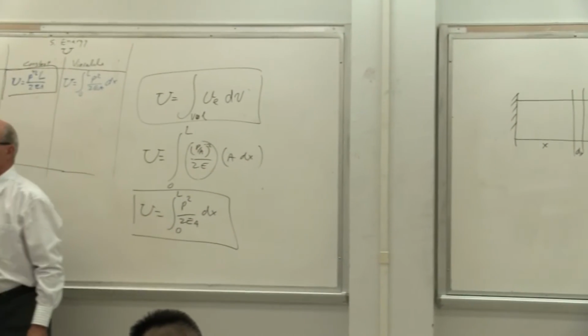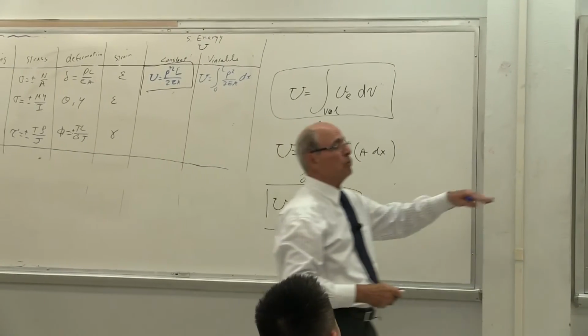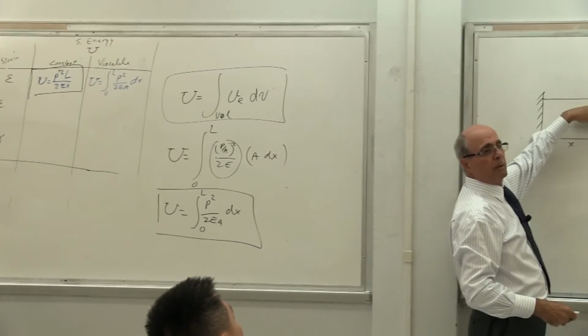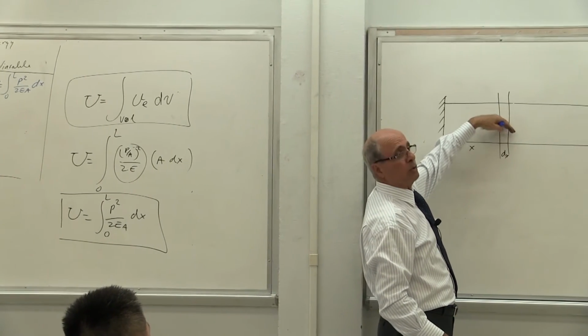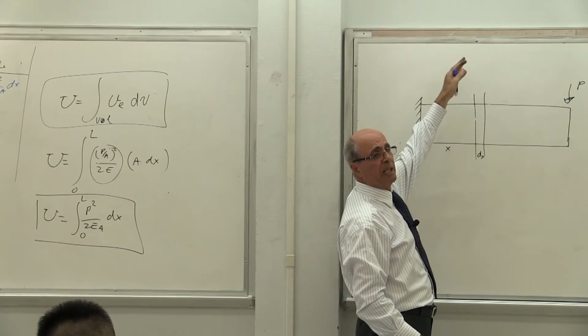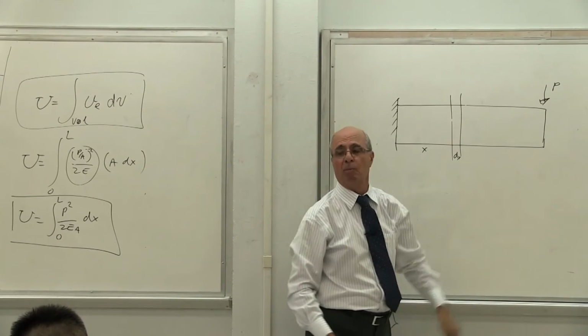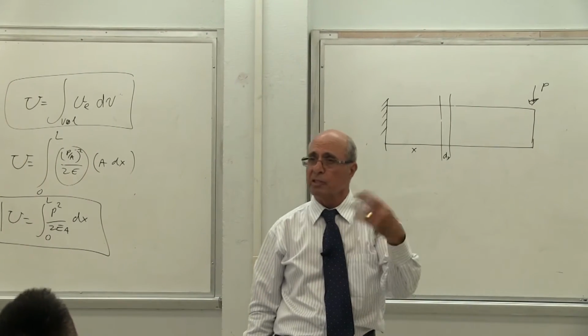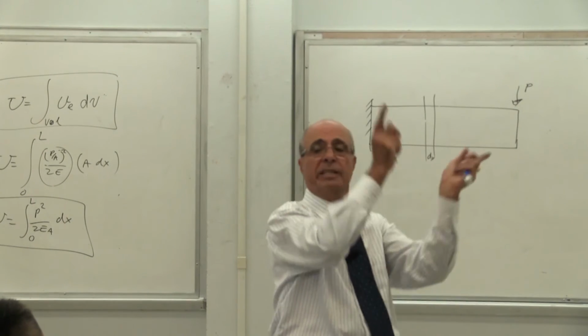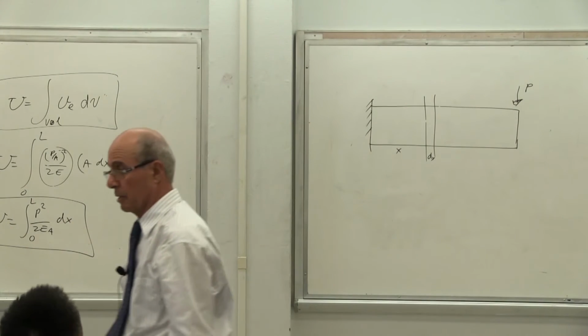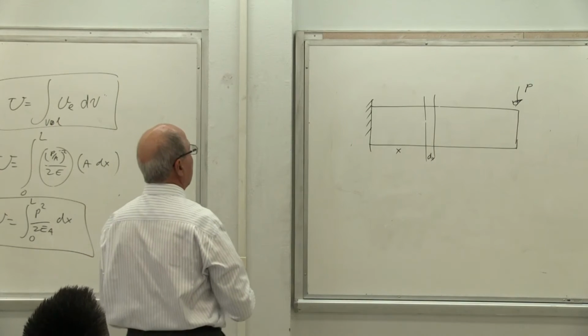Everybody understands that. If y equals 0, you are on the neutral axis. You go up, for example, and you are either in tension or compression, depending on what kind of moment you have. Is that correct or not? So one side is tension, one side is compression, and the change is linear. We know that from the neutral axis, correct? Therefore, I cannot take the volume.